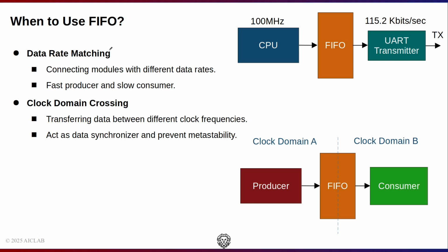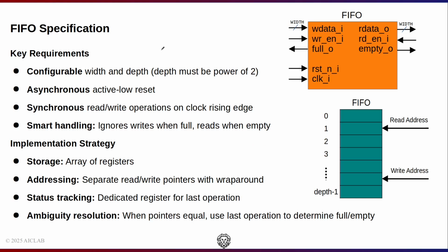In this tutorial, our focus is the first use case, data rate matching. We plan to design a synchronous FIFO. Let's look at the FIFO specification. What are the key requirements? First, width and depth should be configurable, and depth must be a power of 2.